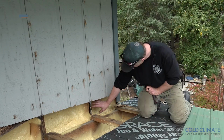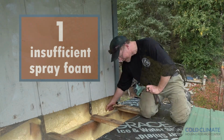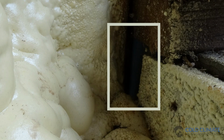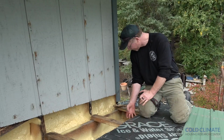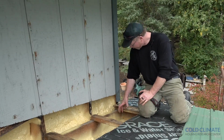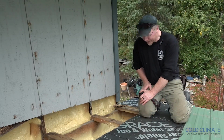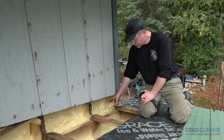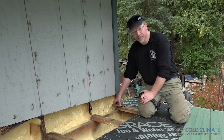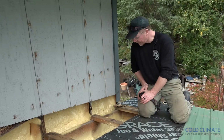There was spray foam applied here to fill this bay, but the smoke test showed us that there's a half-sized hole right here in the corner. I can stick 2 fingers in it, and we know that that goes straight down into the closet wall. So there's a direct air leakage pathway from inside into this bay. I'm kind of surprised that this entire bay wasn't just filled and sealed with spray foam. That would have been the ideal solution instead of placing the fiberglass in here.